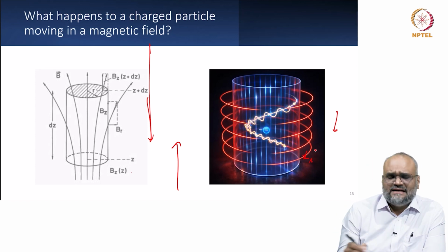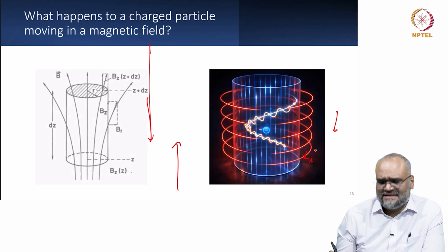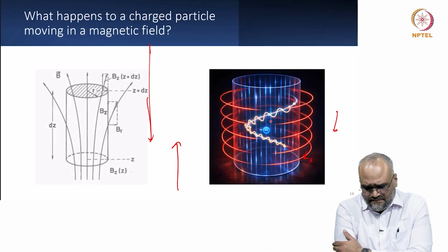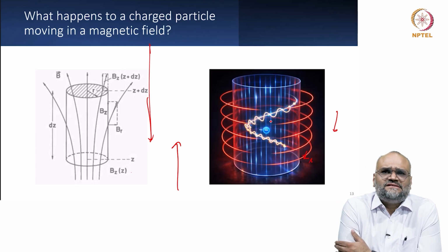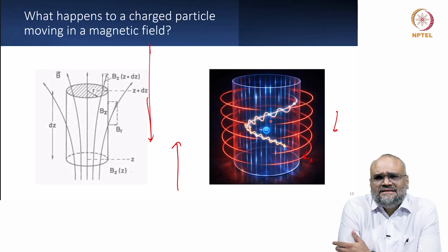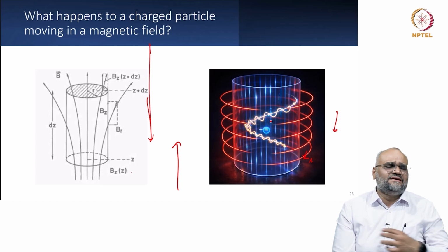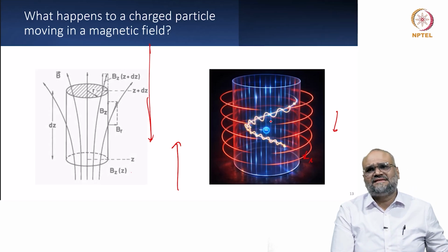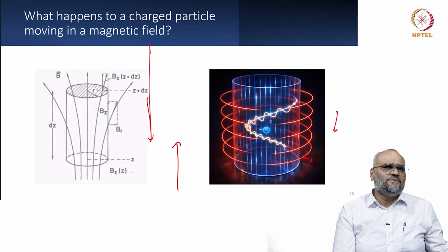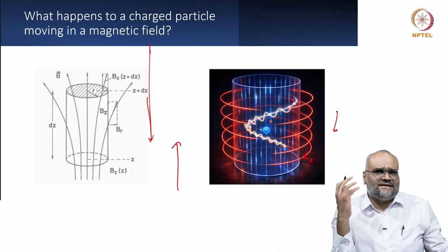When a charged particle, that is an electron, enters this kind of a field, it experiences the Lorentz force and follows a helical path. In some of the older microscopes, you would see the effects of this helical path influencing the image that you record, and you had image rotation. The newer microscopes, because the electron beam trajectory is reasonably well understood, compensate for this image rotation, and the image that you record remains stable with various magnifications. So this is how an electron beam moves in an electromagnetic lens.